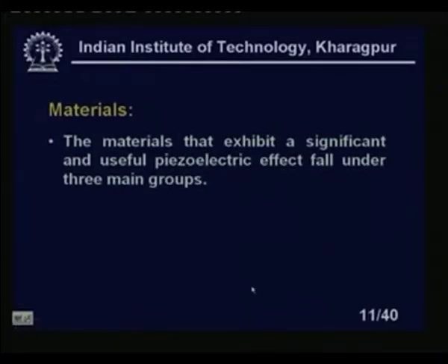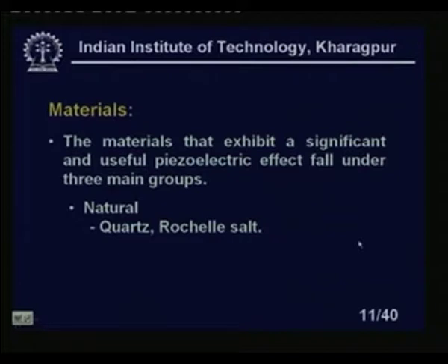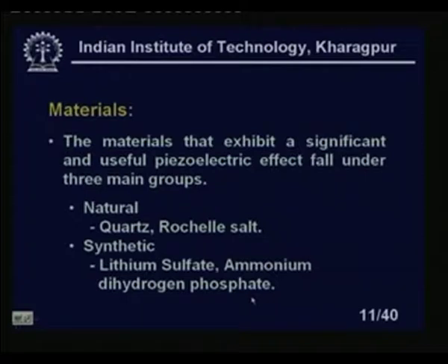The materials that exhibit a significant and useful piezoelectric effect fall under three main groups. One is natural: quartz and Rochelle salt are the two. Quartz is very commonly used and Rochelle salt is also used. Then you have synthetic: lithium sulfate and ammonium dihydrogen phosphate. These are two different synthetic materials. These two materials also have the piezoelectric effect. That means, if you apply pressure, a voltage will be developed. If you apply a voltage, pressure or force will be developed across the plates.